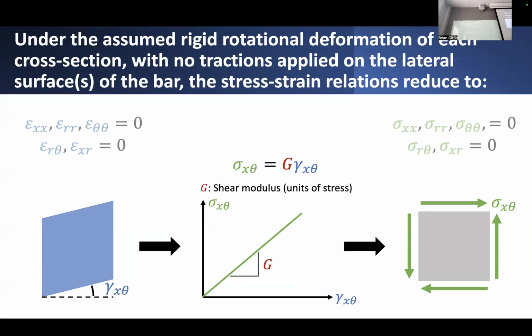Now it's particularly convenient when you're dealing with torsion. Using the shear modulus is a nice way of just relating shear strains and shear stresses, particularly for these torsional shear stresses and strains.